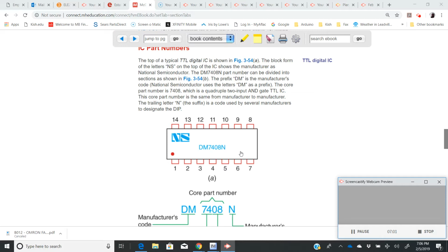Finally, on this, I wanted to say that if you're not sure what the chip is, look on top. You usually see a DM, you might see an LS, whatever, but you're looking for unique numbers, 7408, 74139, 138, whatever. You're looking for those unique numbers on that.